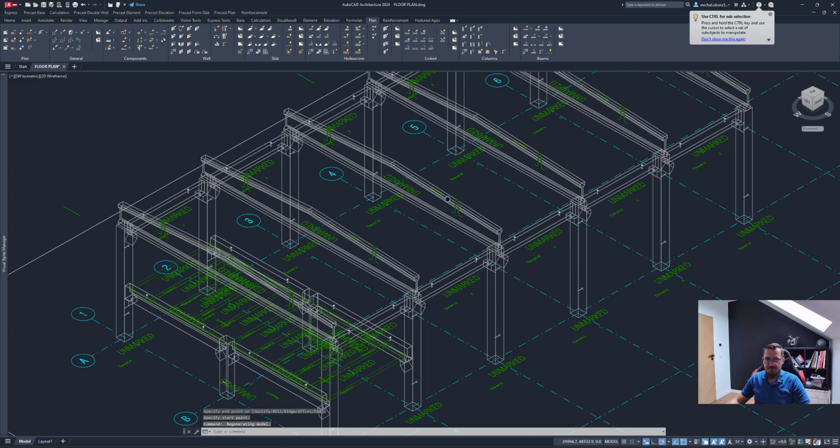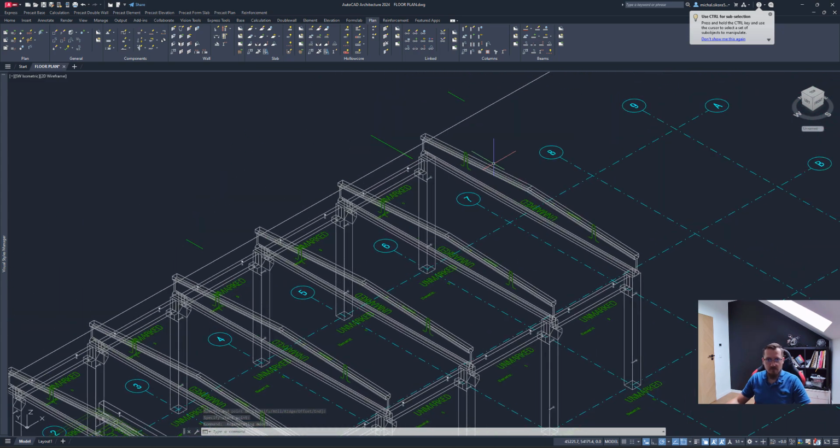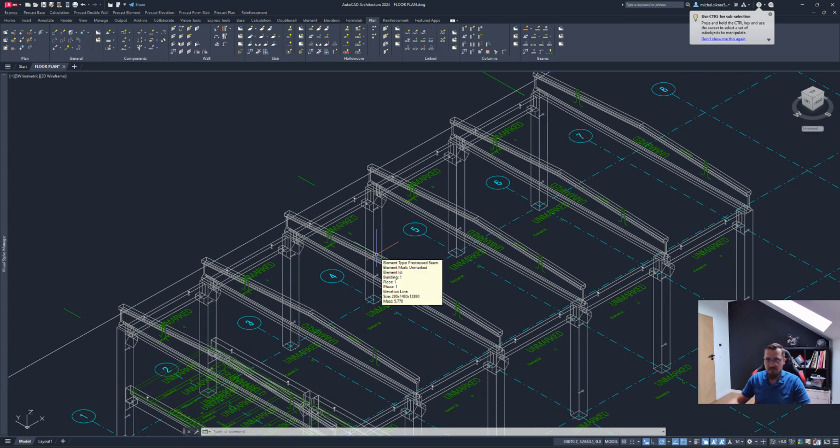And as you can see, we now have sloped columns, sloped beams, sloped pre-stressed beams. Basically, the software automatically recognizes that it's a sloped section, and it symmetrically tries to create the slope along the center of the element. And of course, the element can be as long as you need it to be.